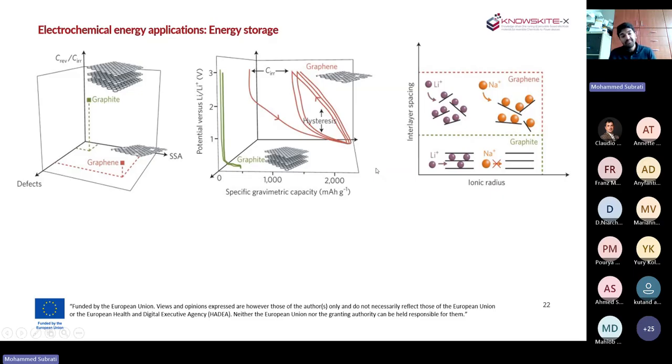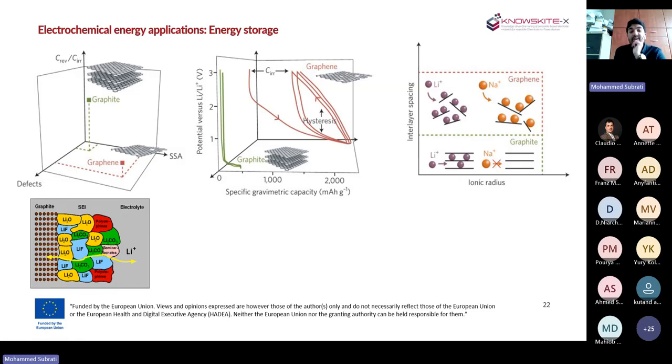We have to check one thing, the formation of the SEI, the solid electrolyte interface, which is basically a passivation film, a soup of lithium byproducts that forms with time, but at the same time allows the shuffling of only one thing, the active charge carrier, which in this case is the lithium cations. So what's so different between graphene and graphite? Graphene layers are much more exposed compared to graphite.